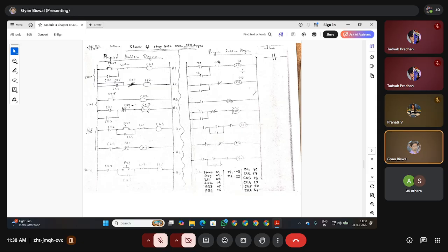So in the programmable part, we are going to program here in this way. Start operation, I am keeping the address number 1. Stop operation, address number 2. You know that I have already shown you in the instrument list how we address these numbers in a real-life scenario. But for our easy understanding, here we have given some 2-digit numbers. We are considering six inputs, and start, remember, is PB1, and stop is PB2 already. That's why I have not mentioned PB1, PB2 separately here.